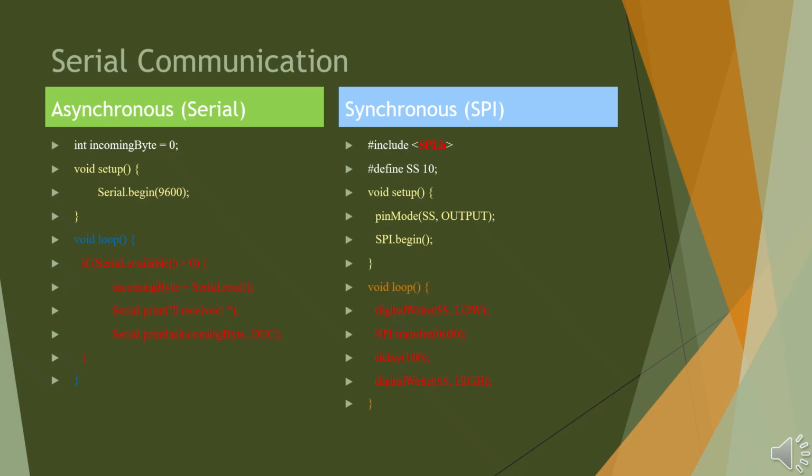In short, the UART example shows simple, direct communication ideal for text and debugging, while the SPI example shows faster, synchronized data exchange suitable for sensors, memory chips, and displays. Together, they illustrate how the hardware configuration and timing mechanisms differ between asynchronous and synchronous serial systems.